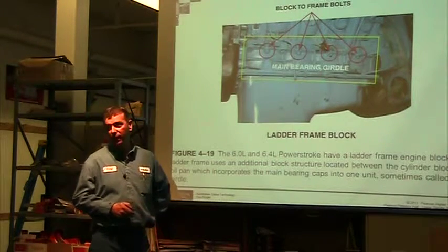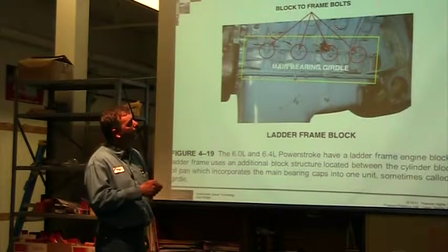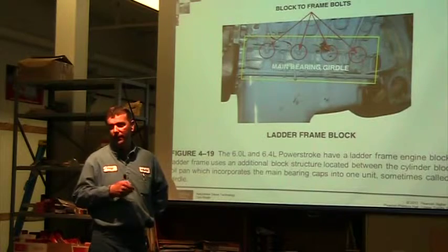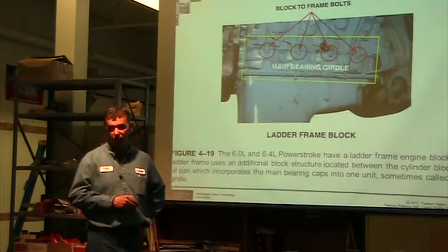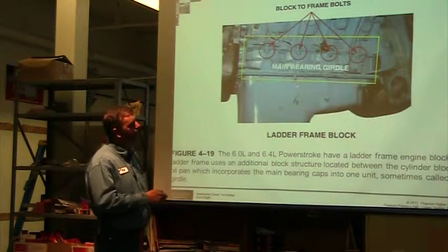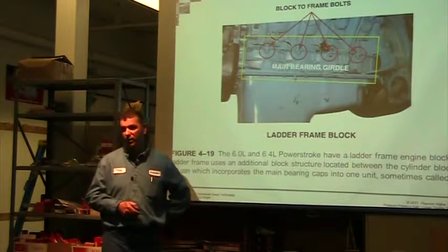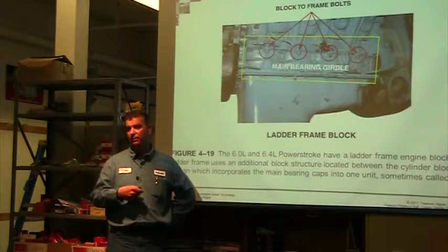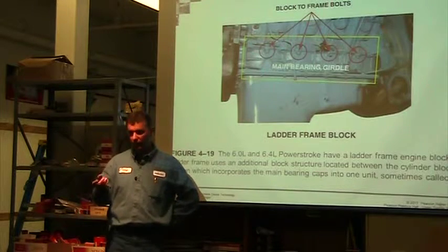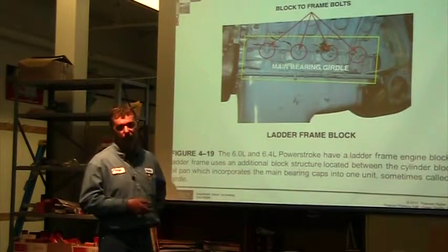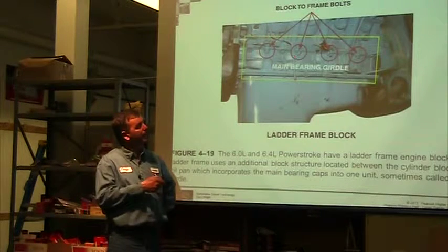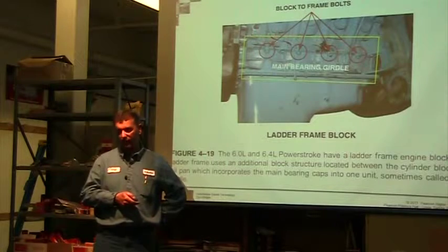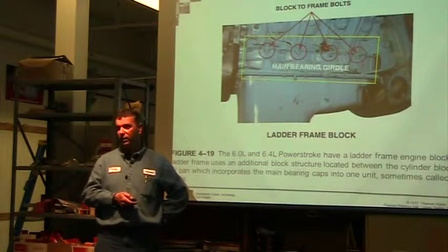As a technician, every single time I add a cover or a plate, I have to add a gasket or a sealing surface. So one of the disadvantages is that it's another sealing surface. I've got a gasket between there, or we form a gasket with liquid sealing. Anytime I have surfaces come together, I have to have some way of sealing it, and that's another potential leak point.